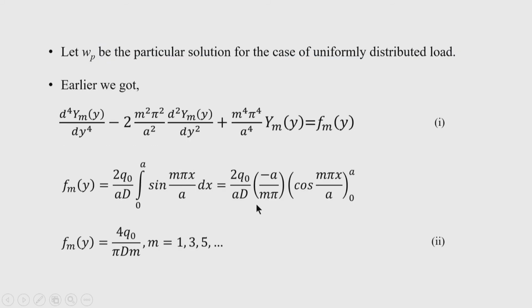All right. Now, let W be the particular solution for the case of uniformly distributed load. Here, there are different ways of solving the non-homogeneous differential equation. One very attractive method for our physical problem, that is the problem encountered in structural mechanics, is the method of undetermined coefficients. In this method, observing the nature of the forcing function, or this non-homogeneous part, we can assume